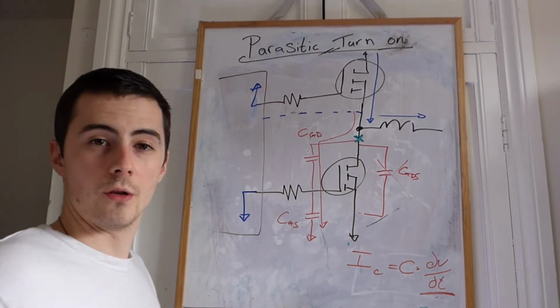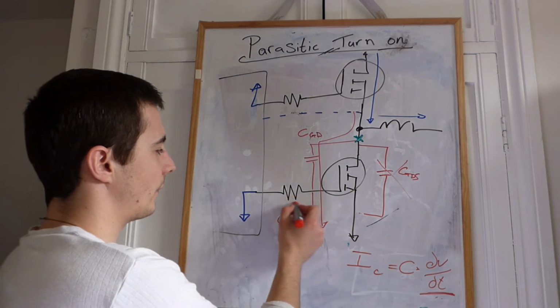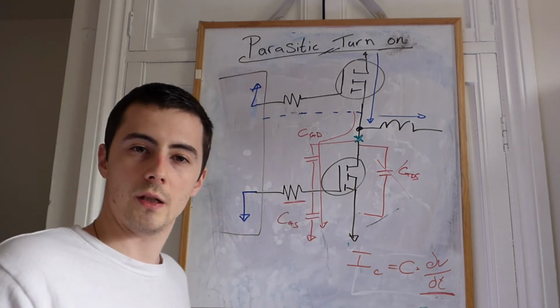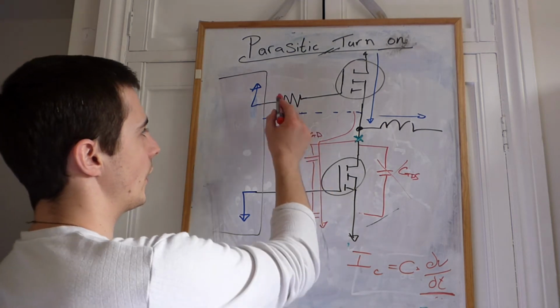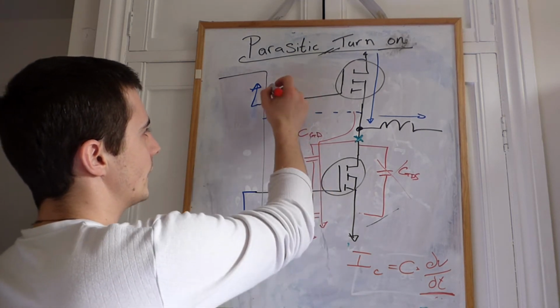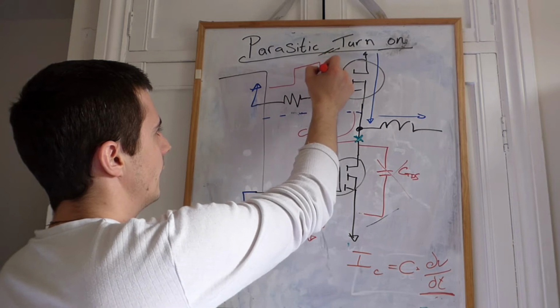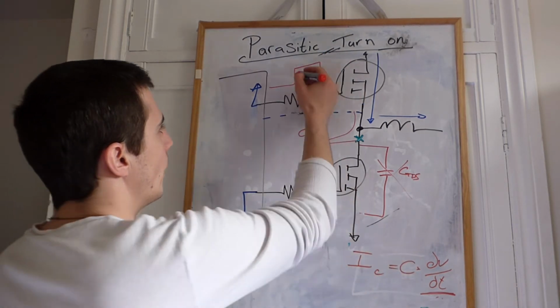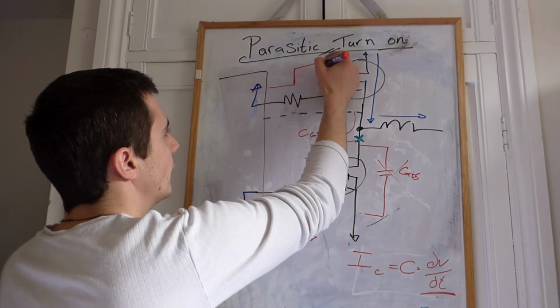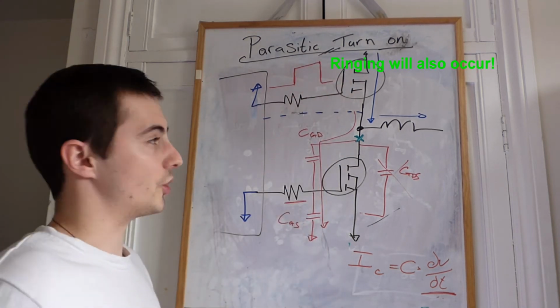Well, yes, we do. Because generally, like I said before, we have these what are called gate resistors. Now, gate resistors smooth off these transitions. So without a gate resistor, if we were to drive this point high, so we want to turn that switch on and then off, what we get is very sharp edges on here, which is generally not good